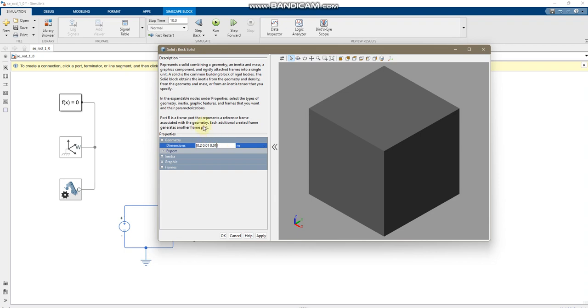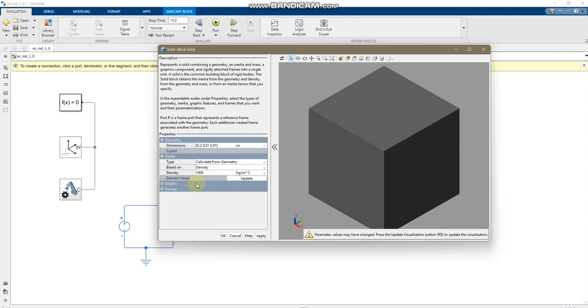So that's it with regards to the geometry. We're going to specify it using primitives. By primitives, I mean how long some dimension is. And now we can specify the inertia. I'm going to specify it based on mass, not density. First, I'll specify it to 0, and you can change it later based on your requirements of the system that we are going to study.